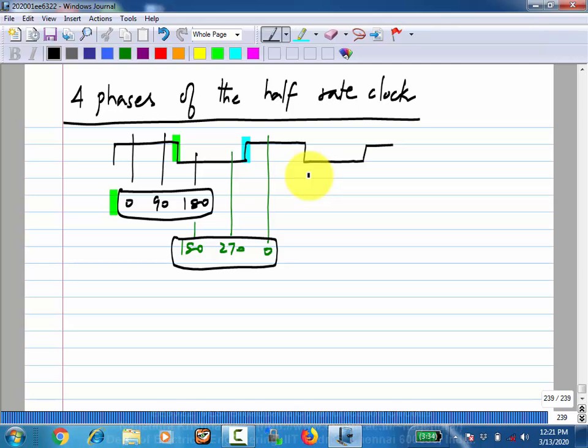From very low frequencies if you start off, if you let's say double the rate and half the amount of circuitry, you will consume the same power. But as you go to higher rates, it turns out that the implementation becomes more and more difficult and the power increases more than linearly with frequency. So at that point, it makes sense to go to half the rate and then do this. Okay. Yeah, you still have to produce enough edges to cover all the samples. Okay.